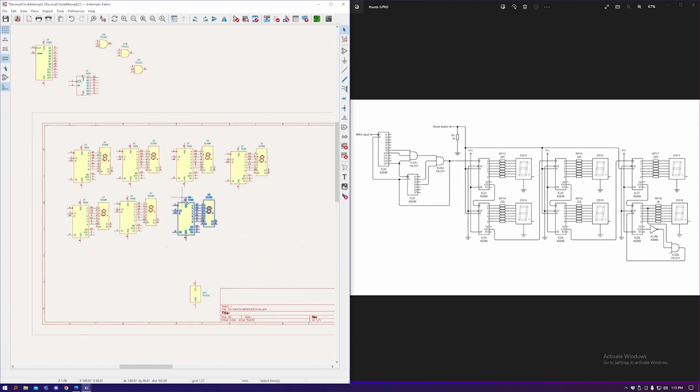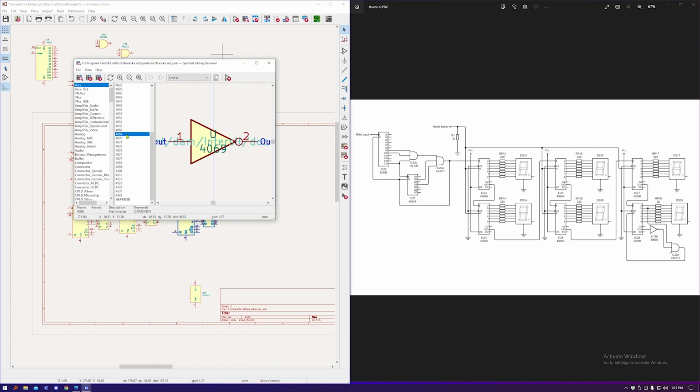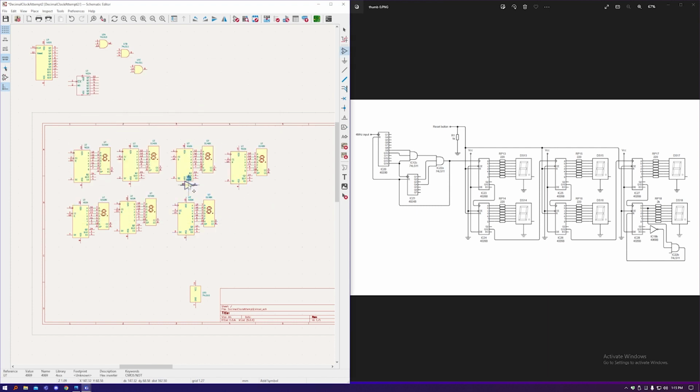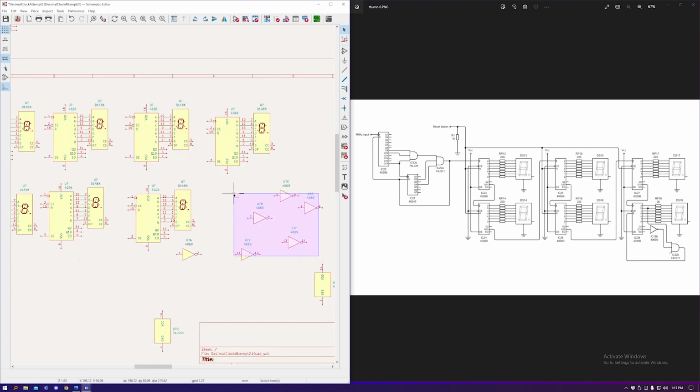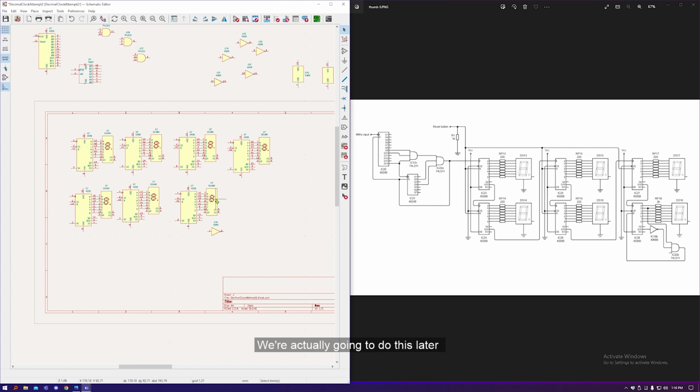Right, other components that we have on the circuit is the 4069 inverter, which they will definitely have because that's very common. 4069. This will do the same thing as the AND gate, so it'll add 6 of these and then the power to the chip. We only want 1 of them, so we'll use A, and the rest of them we'll throw away for now. It's fine to put stuff out of here, and if you've got a really big schematic you can change the size of this sheet, although there's a nicer way to do it with multiple sheets that link together, which I'll show in a future video.